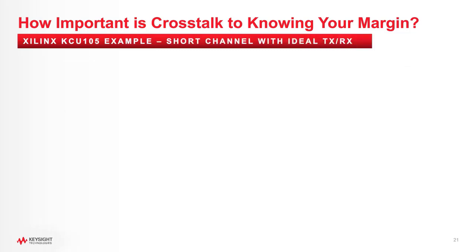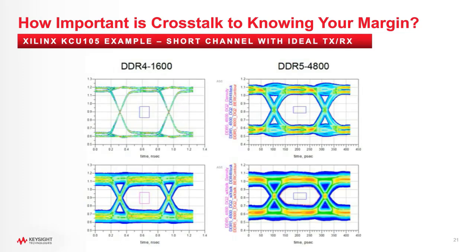Let's move to this slide. Okay, so for instance, when we looked at this one, you could also ask the same question: were these near end crosstalk? Were they far end crosstalk? Well, along the data bus, you're either always transmitting or all receiving at the same time. So your nearest neighbors are likely to be, if you're transmitting, they're going to be transmitting too. So in this case, it's near end crosstalk which is being excited. Great, thanks so much, Stephen.